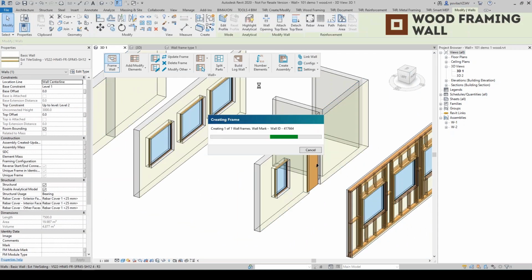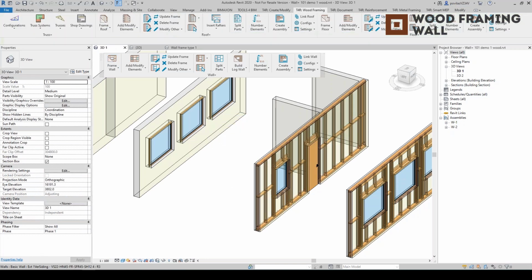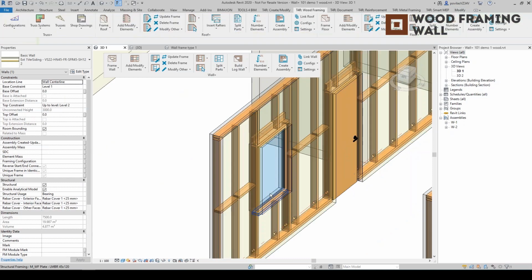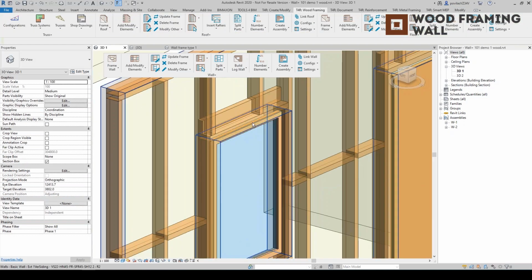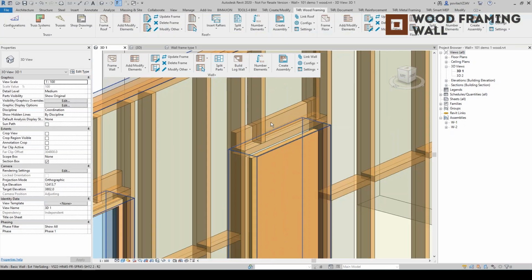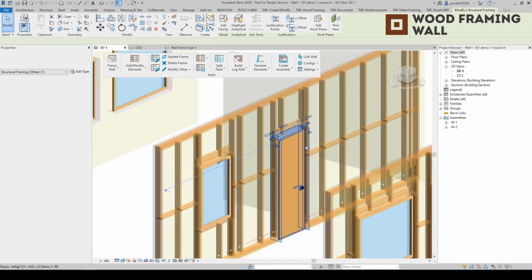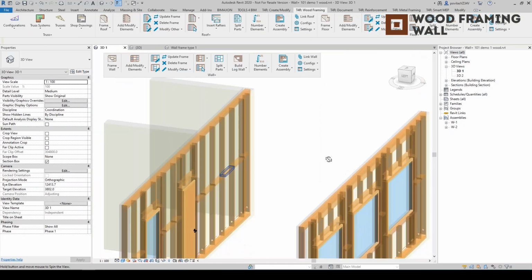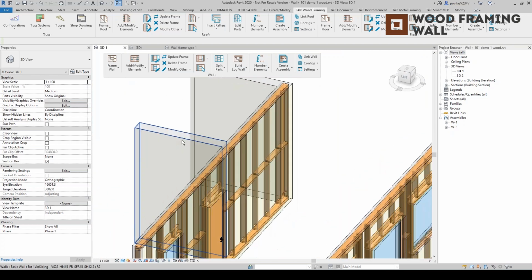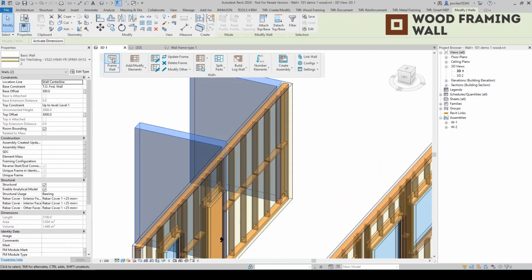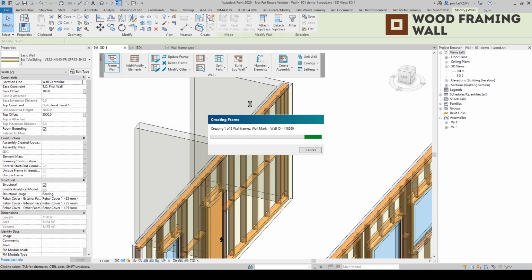Wall Plus not only distributes the structural framing, we are also dealing with other layers of the wall, actually the entire multi-layered wall panel, that we can use Wall Plus to do the work for us. In this case we have a slightly different variation for window framing and door framing. We have headers set up. We have noggings at 1200, I believe, distance. And for those two here, I can multi-select more than one wall at one time, and it's going to frame those 2 walls.